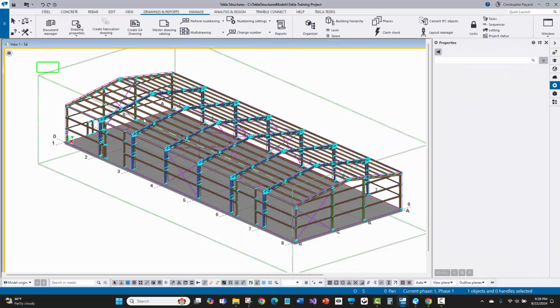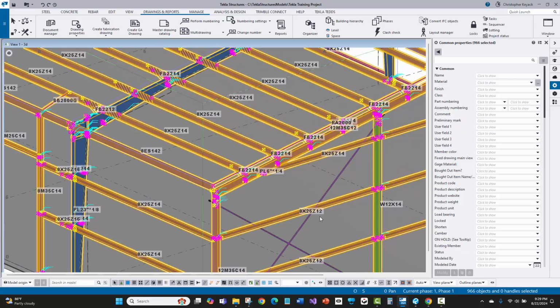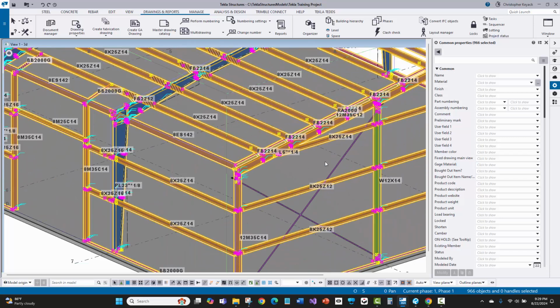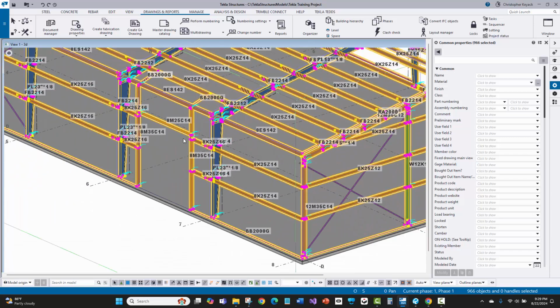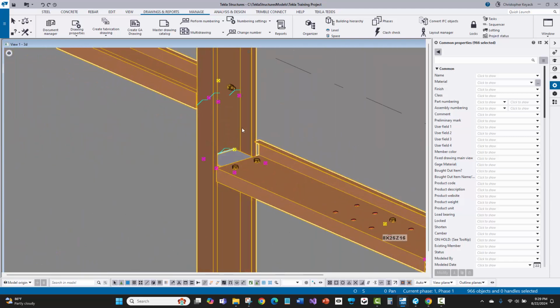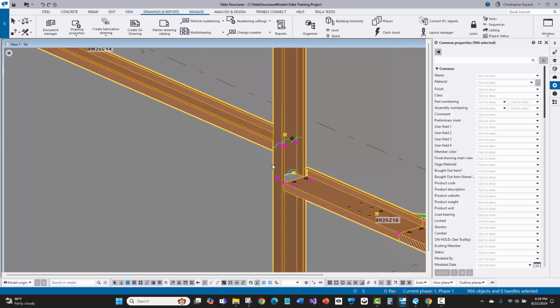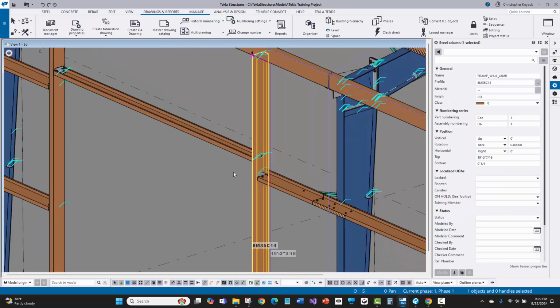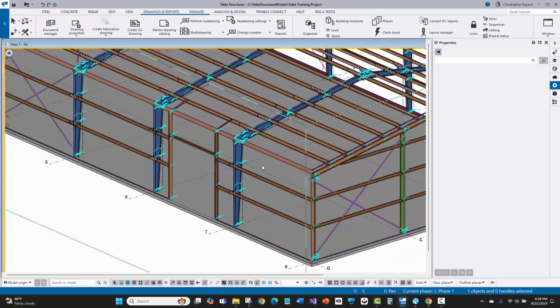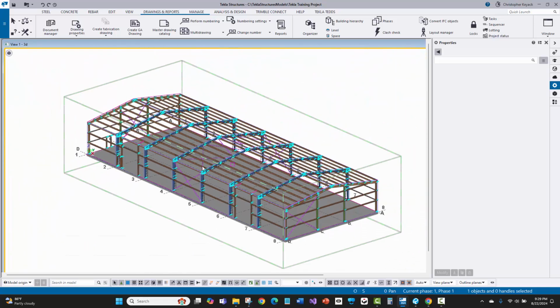And then now if I window around the model using that filter, it's going to select everything, but it will exclude our cable braces. Now you may exclude your Girts and your Purlins, depending on if you're doing welded clips or not. So here on the jambs and the headers, I've got a lot of welded clips going on, so I'm going to need to make shop drawings definitely of the jambs, but maybe I don't need to do that of the Girts or the Purlins. So you can choose to control what things you want to make the drawings of.